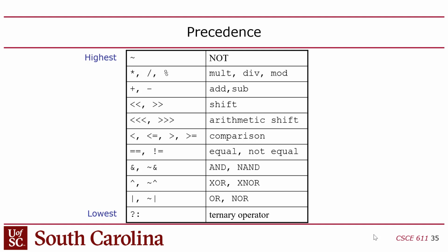Why? Well, in C and Java, the decision of whether you're doing a logical or an arithmetic shift is determined by the data type, the variable declaration of the thing you're shifting, right? So if you declare a variable as unsigned and you shift it in Java, it's going to do an unsigned logical shift. But if you declare a variable as signed, like an integer, and you shift, it'll be a signed shift, right? But in Verilog, we don't have signed and unsigned. There's logic, right? So as a result, we need to be able to differentiate those by these different operators.